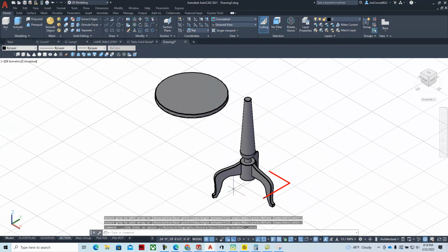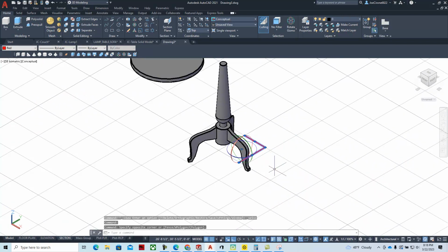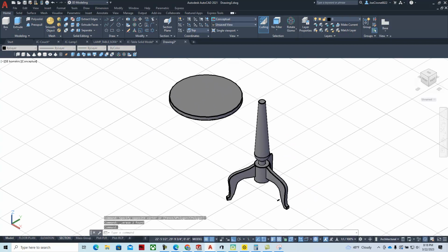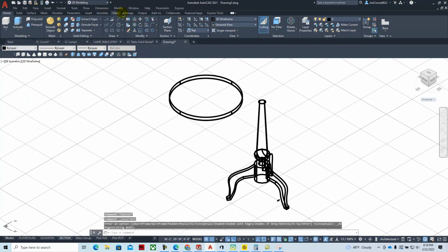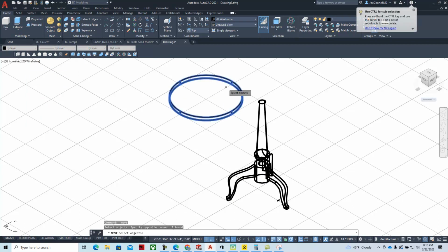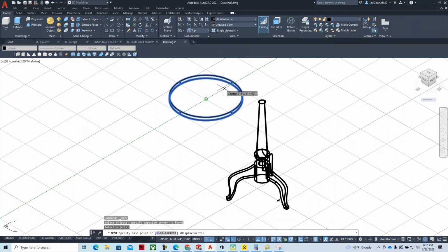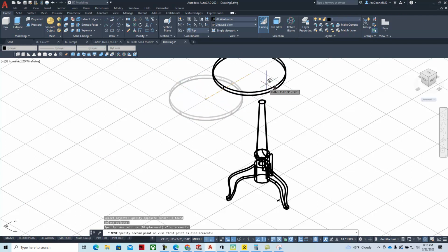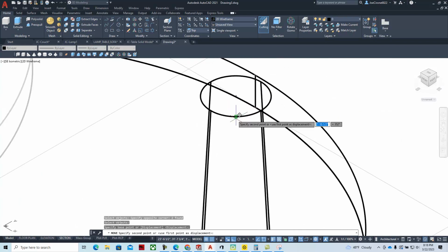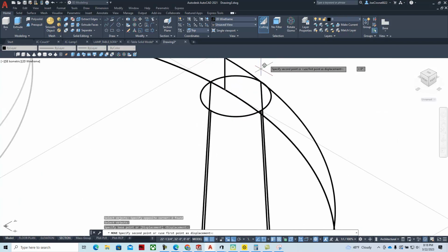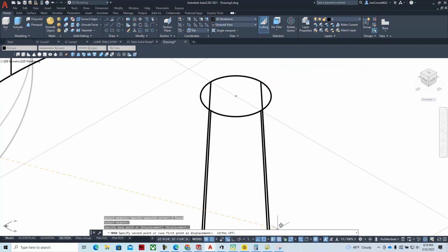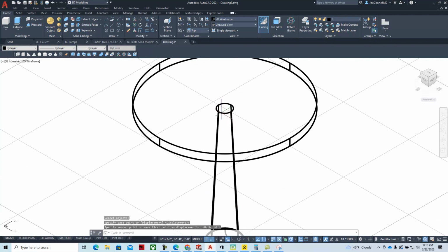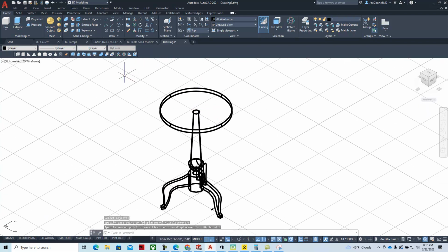There we are. We can clean this up. We don't need to see that. And then what we'll do is we'll put the table on the top. I'll use a wireframe to do that, and I'll just use a move command where I'll select the object, hit enter, acquire the bottom center point. You can kind of see it track to the top one there, left a little witness mark, and we'll bring that then here to, it's fighting me because I think ortho's on, yeah, to here. There we go.